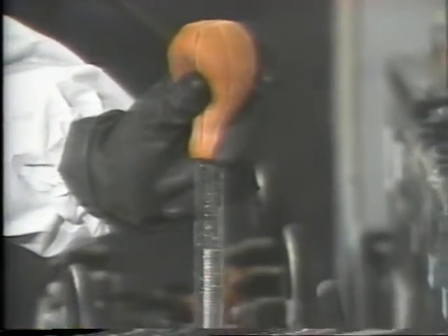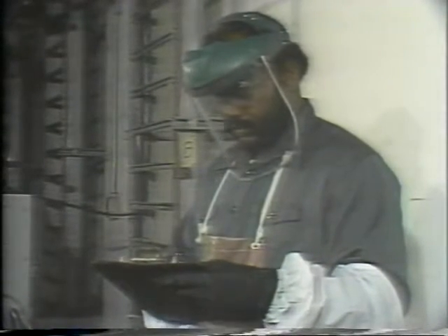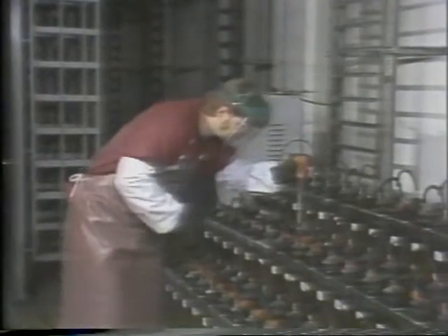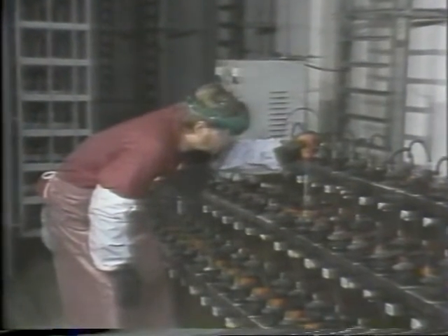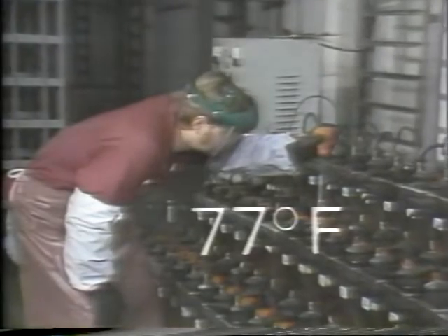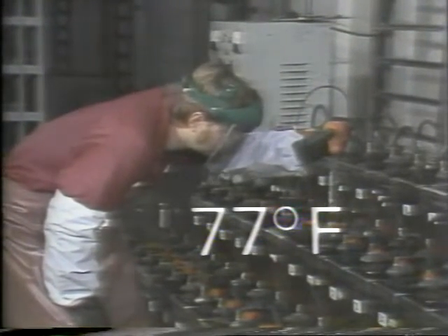In order to get accurate specific gravity readings, 2 considerations are necessary. First, the hydrometer tests should not be made right after water has been added to the battery. After adding water, it's best to charge the battery for a specific period of time to give the water time to thoroughly mix with the electrolyte. Otherwise, the water will sit on top of the denser sulfuric acid solution, giving you a false reading. The second consideration is temperature. Most hydrometers are calibrated to give correct readings at 77 degrees Fahrenheit, 25 Celsius.